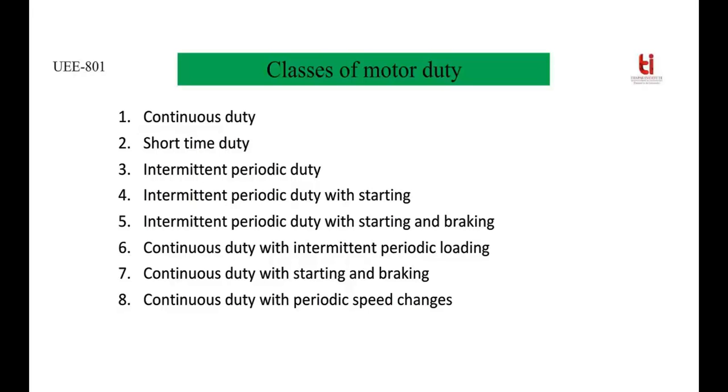Based on that, there are different classes of motor duty, and these classes are continuous duty, short time duty, intermittent periodic duty, intermittent periodic duty with starting, intermittent periodic duty with starting and breaking, continuous duty with intermittent periodic loading, continuous duty with starting and breaking, continuous duty with periodic speed changes.